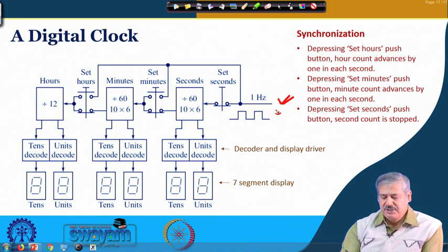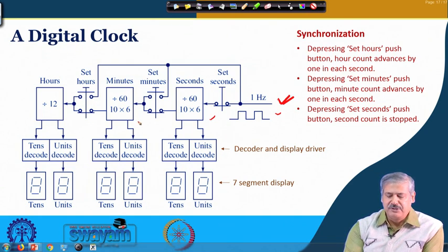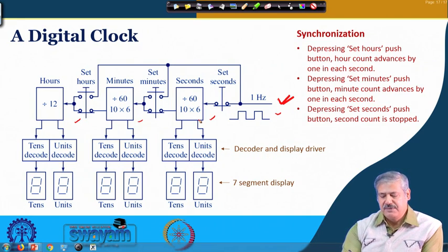This is going to the seconds, seconds is feeding the minutes, and minutes is feeding the hours. So, every 60 seconds, you can have a mod 6 and mod 10 together, and for minutes also a mod 60, and for hours you need a mod 12.